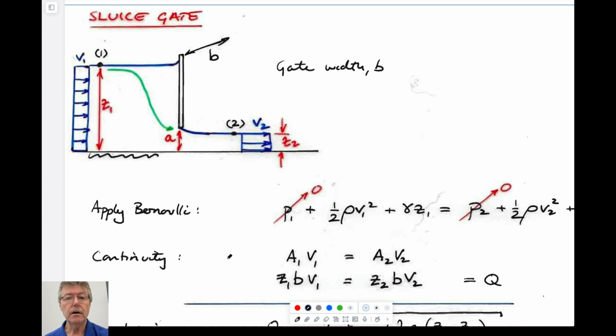So if you are on the surface, then you can use exactly the same deal. You can look at a weir. This is an undershot weir rather than overshot weir. An overshot was the one that we looked at in the video in the run-up to the class. We can do exactly the same thing. This is kind of a free jet. If this was an infinitely big reservoir, if Z1 was much bigger than Z2, then we could probably write that V1 is equal to 0. But if not, we can't.